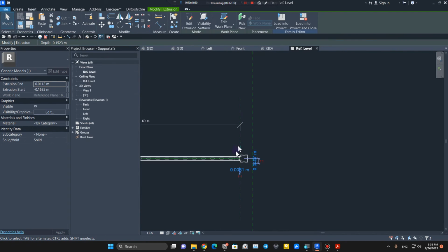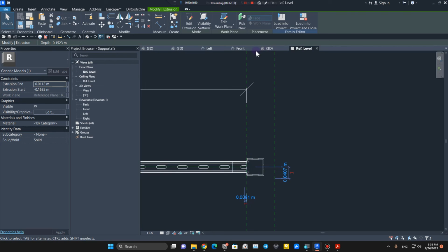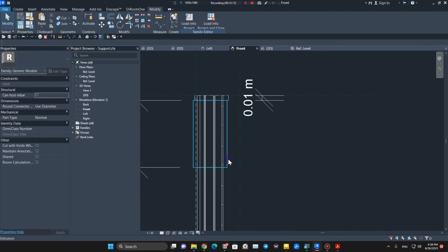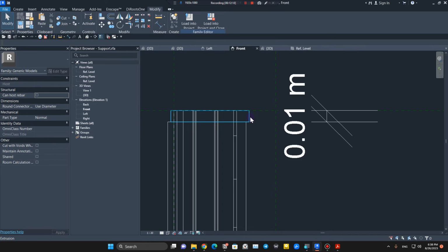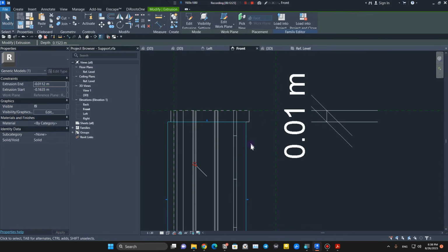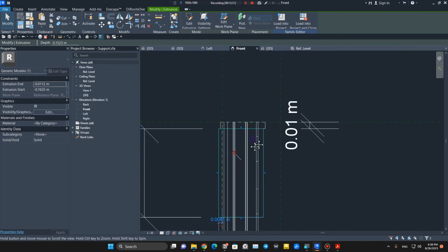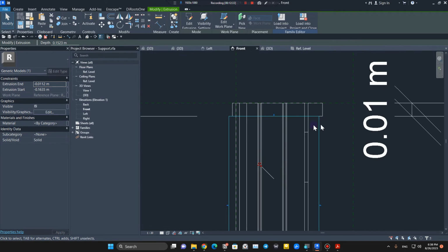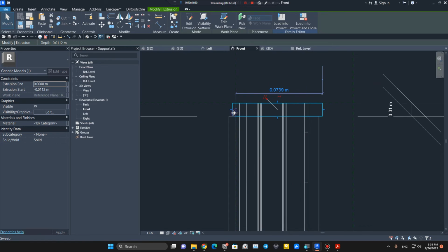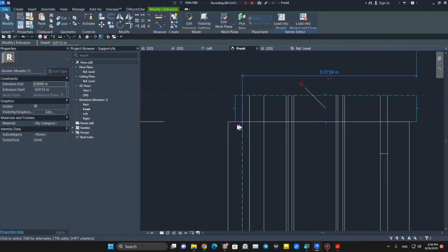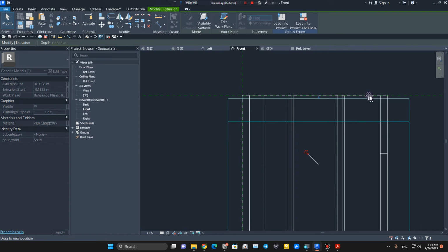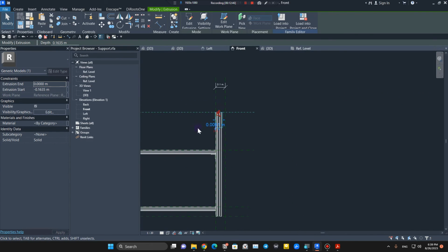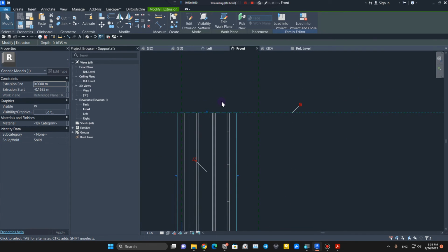We have to do the same thing for the HSS profile 2. Let's go to the front. We did it for HSS. We need to do it for this part. I made a mistake in here. I've assigned 1 centimeter to this one. I'm not going to redo it, but make sure to assign 5 mm to this one. And let's do the same thing for this one. Or I can just delete this and bring it to the top one, because I have taught it on the other side, I'm not going to spend time on this part again.